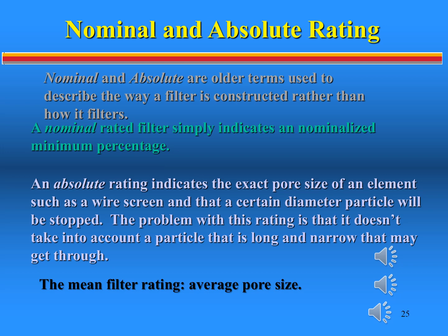The absolute rating, or cutoff point, of a filter refers to the diameter of the largest spherical glass particle, normally expressed in micrometers, which will pass through the filter under laboratory conditions. It represents the pore opening size of the filter medium. Filter media with an exact and consistent pore size or opening thus, theoretically at least, have an exact absolute rating.